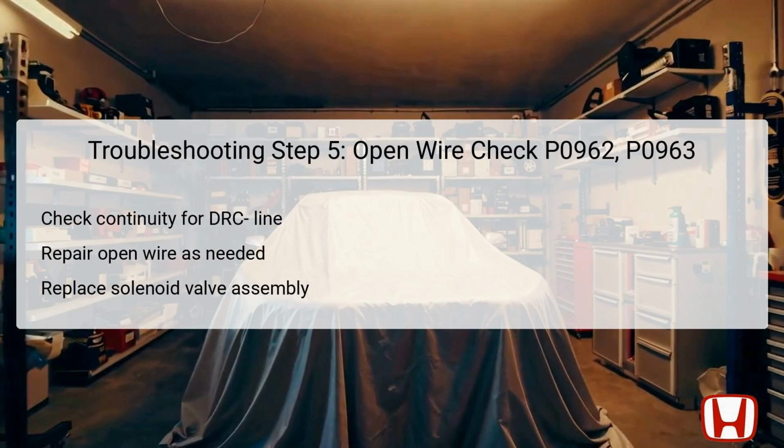In the final troubleshooting step, addressing DTCs P0962 and P0963, we focus on assessing the DRC line for continuity. Ensure that the CVT drive pulley pressure control solenoid valve 2P connector and the TCM 50P connector remain disconnected to prevent erroneous readings. Check continuity between the solenoid valve connector number 1 and body ground.